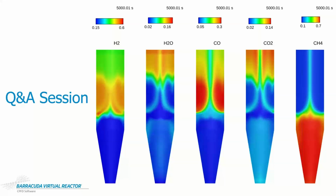Well, I would start by implementing the reduction kinetics as they are, and then there is some plant data that's available. It is limited because some of these processes can be proprietary, but I would start off with the solid kinetics and then just see how your model aligns with existing plant data or validation. So you might be seeing a significant amount of one species that's not observed in that plant data, and that would indicate the need to include more fidelity in your system, to model additional reactions that might be happening between species in the system.